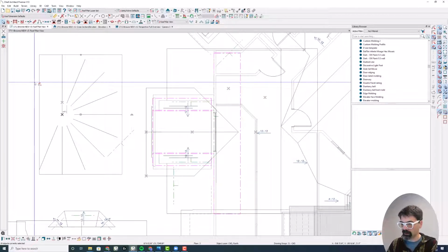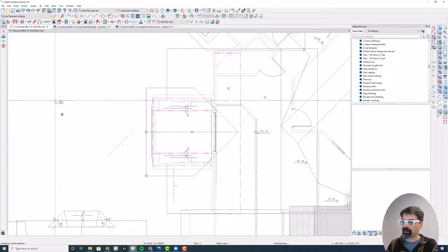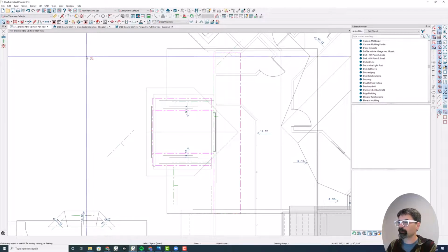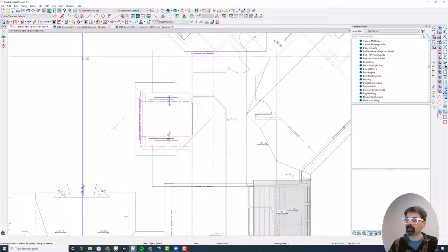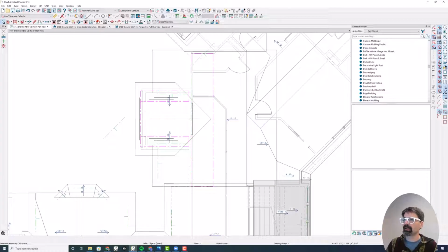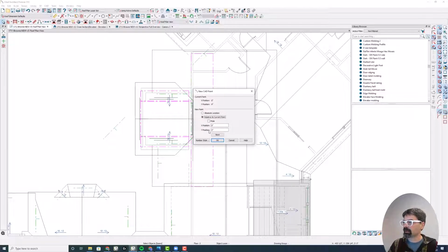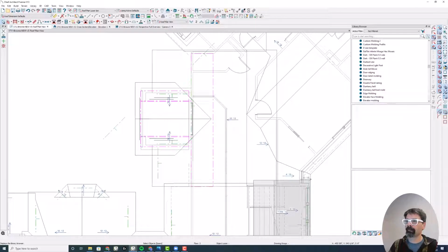Alright, so I'm going to delete these lines, but you'll notice I couldn't delete the points. Now you can, on my toolbar I've got this points right here. Once again, you can go to CAD, Points, Delete Temporary Points. The other thing I should point out is that you can manually input a point according to its XY coordinates. I don't think I have ever used that. You can do it.